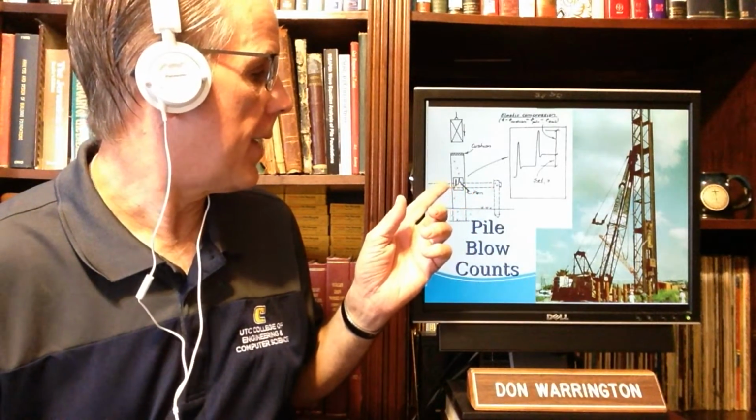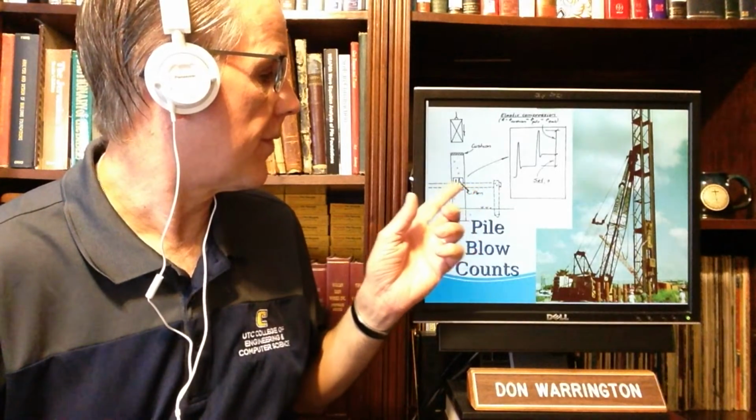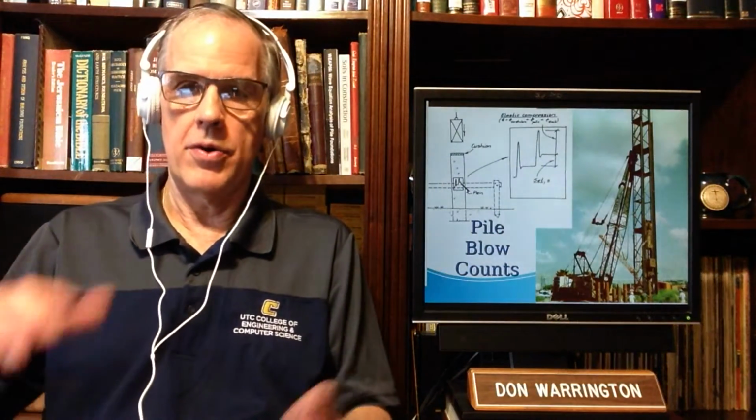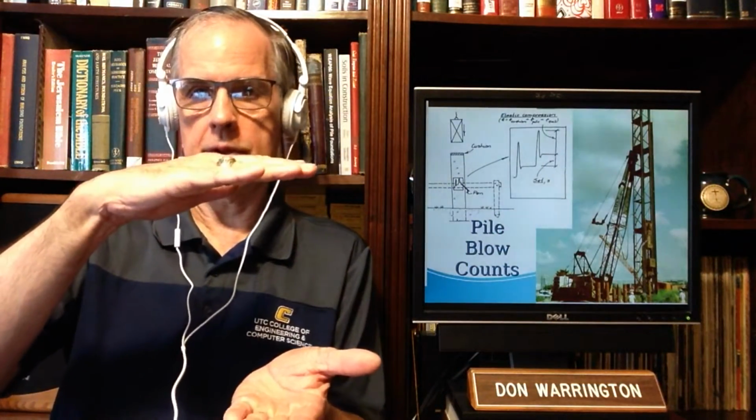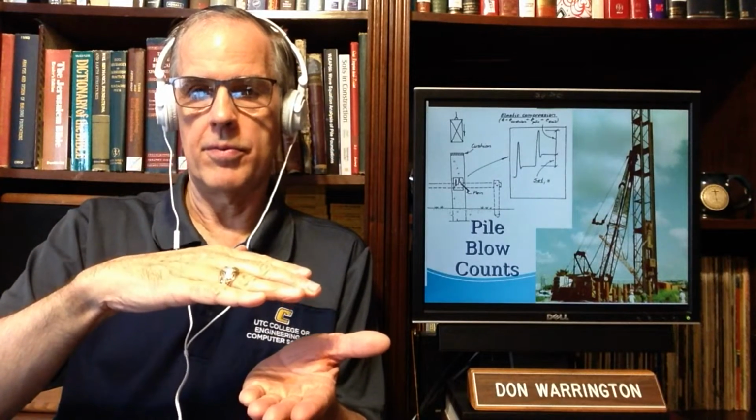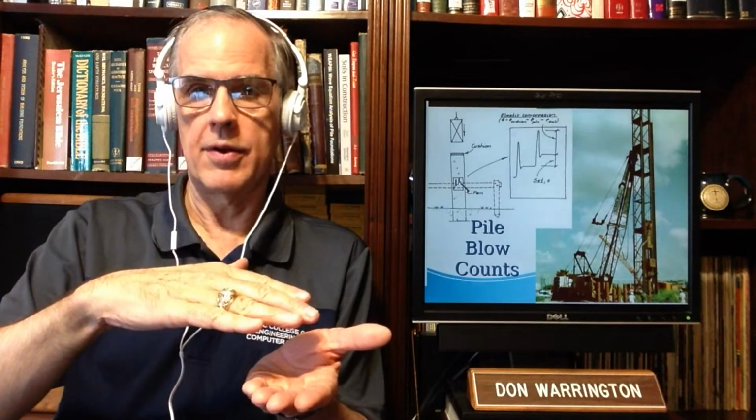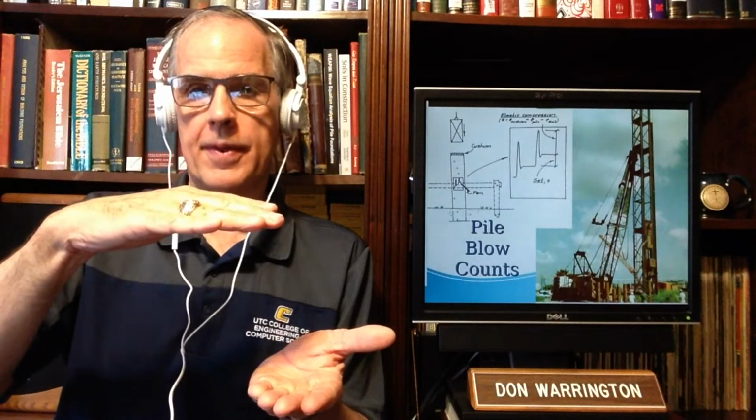If we had a pin that advanced across the front of a pile and we noted what it looked like, we would see that with every blow the pile head goes down, or wherever we're measuring goes down, and then it comes back up, and then eventually it steadies out. What that signifies is that in the initial impact, we are compressing the pile elastically.